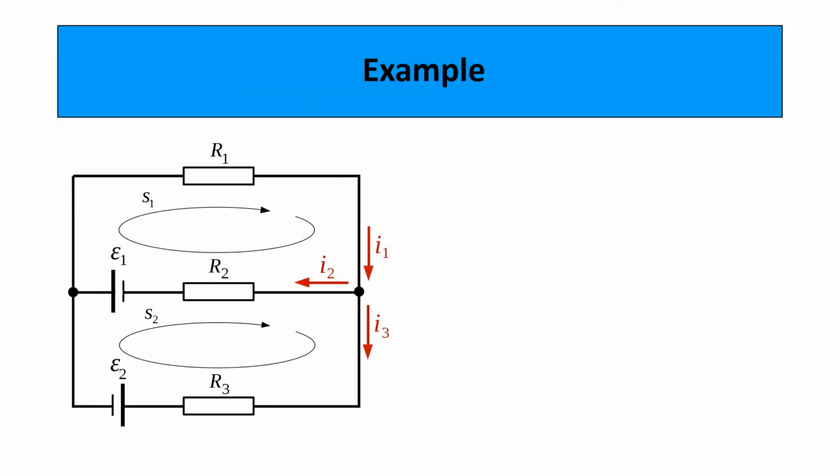To understand Kirchhoff's laws, let us look into this example. You can see two loops in this diagram, say loop 1 and loop 2. Loop 1, let it be A, B, C, D, A, and loop 2, let it be A, B, E, F, A. Next step is to assume current directions in these loops. For loop 1, let the assumed current direction be like this, that is in a clockwise direction. For loop 2 also, we can assume the clockwise direction. You can assume the direction either clockwise or anti-clockwise.